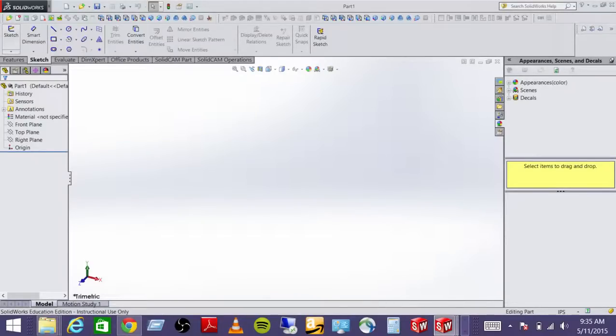You'll see that you can start sketches, you can dimension sketches. You've got geometry sketch tools here: points, lines, circles, arcs, splines, polygons. You can trim. We'll go into convert entities. You can do things like mirror patterns, sketch patterns, move entities, that sort of stuff. This is your most important toolbar within the command manager because that's where you start everything.